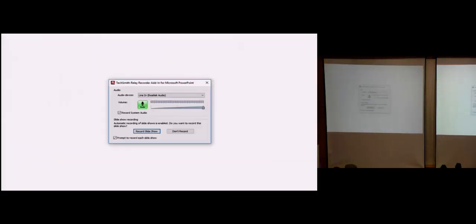So for example here, the question is 0, let's say 4 bits, minus 0. So it is 0 minus 0, correct? So this 0 is this one, and minus 0, and this one I need to specify as 2's complement, correct? So this 2's complement means I flip, plus 1, correct?